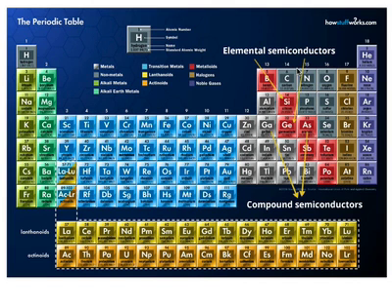There are also other kinds of semiconductors, compound semiconductors, where you use 2 elements to form semiconductors. The most common one is gallium and arsenic, Ga and As. If you put them together, you get gallium arsenide. Now, gallium arsenide is very, very important, primarily for LEDs, light-emitting diodes, all kinds of optoelectronic devices. So everything that drives the internet, for instance, with fiber optics, is based on laser diodes. All of that is driven by, not gallium arsenide in particular, but these kinds of compound semiconductors.